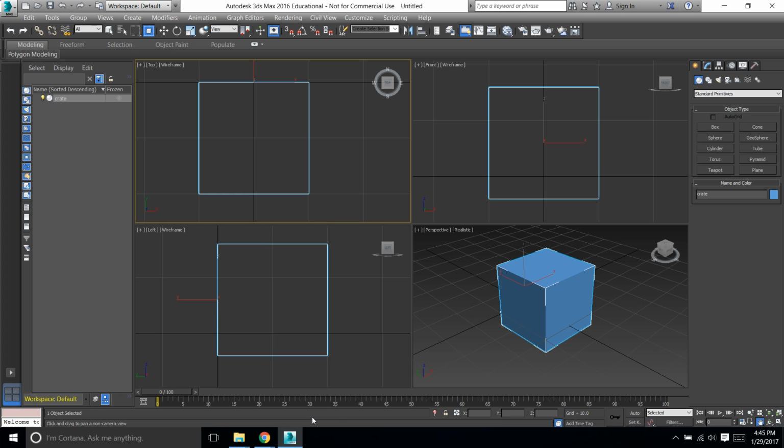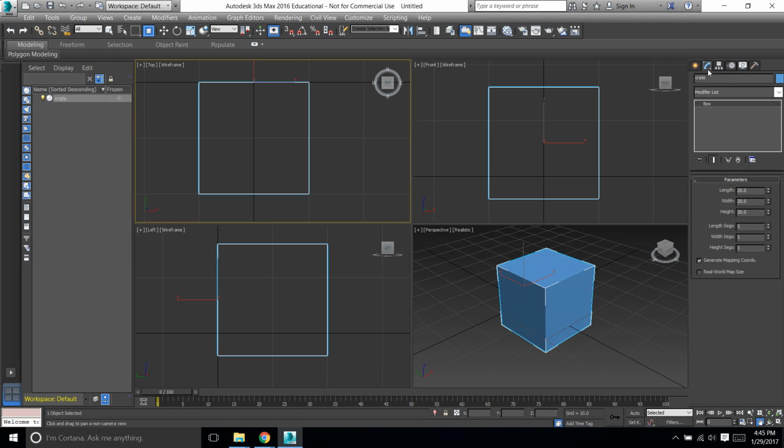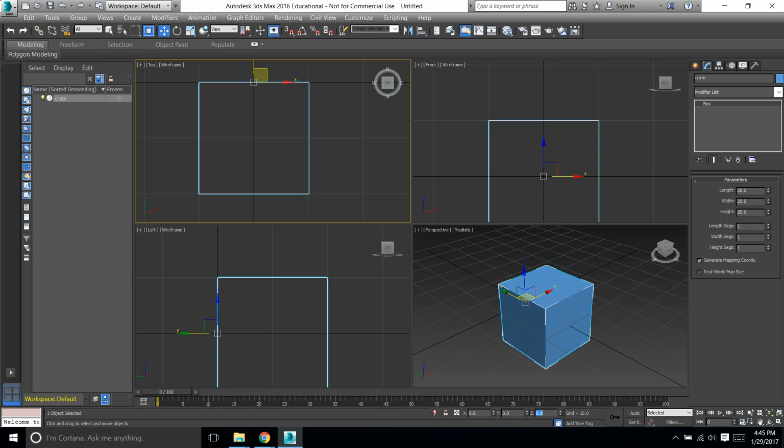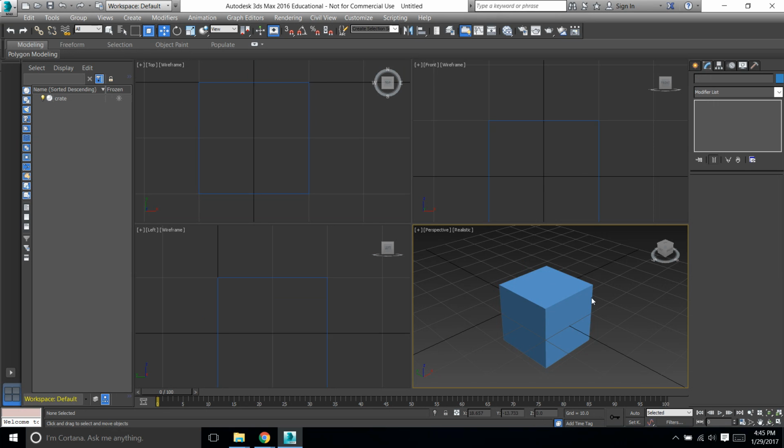All right, I went ahead and started off a little bit here with a box. I used my create, I made a box, I changed it to 20 by 20 by 20 in the edit poly mode. You can see if you hit your modifiers there, those show up. Down here, if you hit your move commands, you can see the coordinates. I changed the coordinates to 0, 0, and I guess I want them all at 0. So let me change this last one, 0, 0, 0. I'm going to leave that thing sit right at the dead origin of this thing, okay?